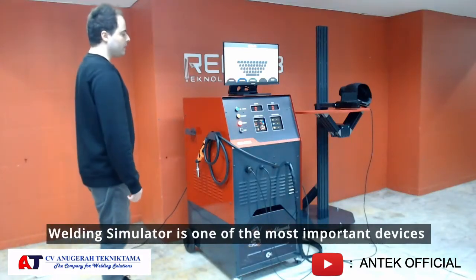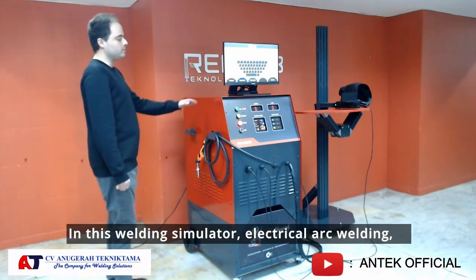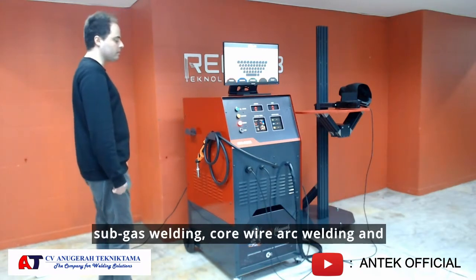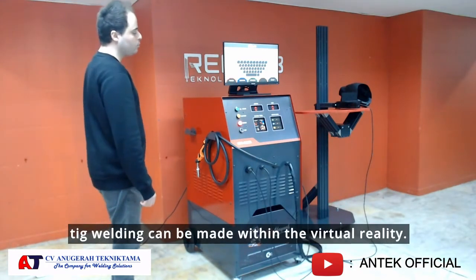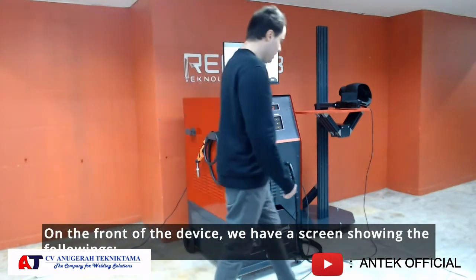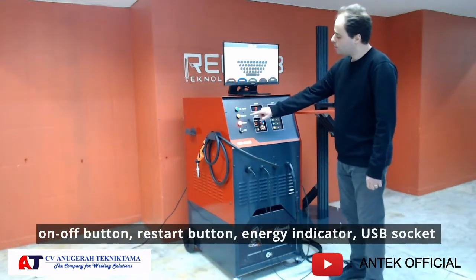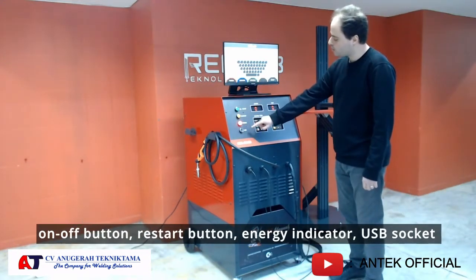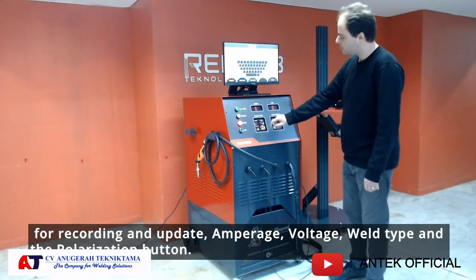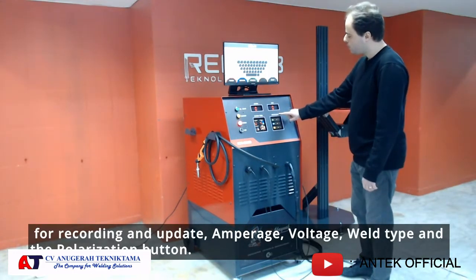Welding Simulator is one of the most important devices in welding trainings. In this welding simulator, electric arc welding, submerged arc welding, core wire arc welding, and TIG welding can be made within virtual reality. On the front of the device, we have a screen showing the following: on-off button, restart button, energy indicator, USB socket for recording an update, amperage, voltage, weld type, and the polarization button.